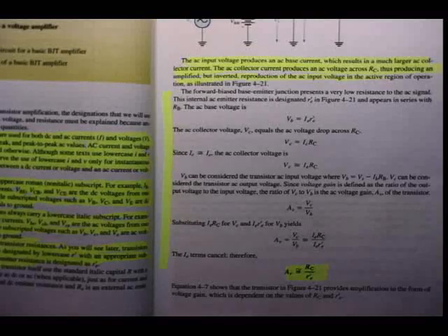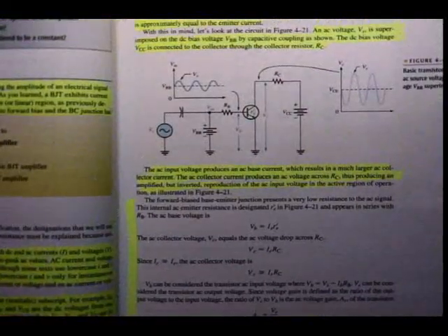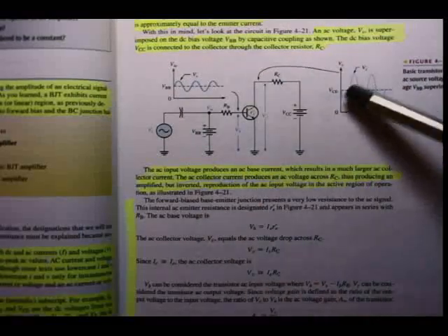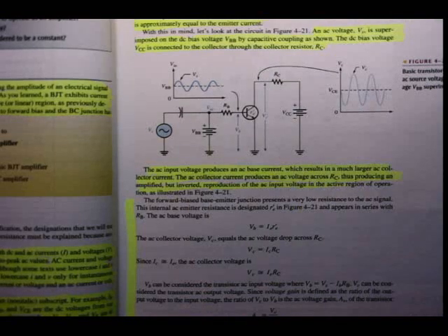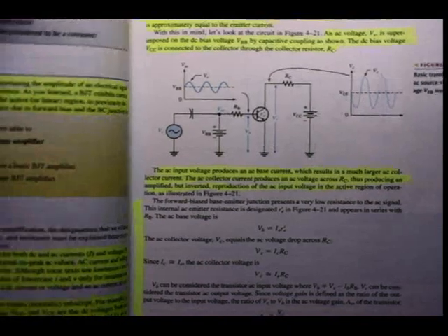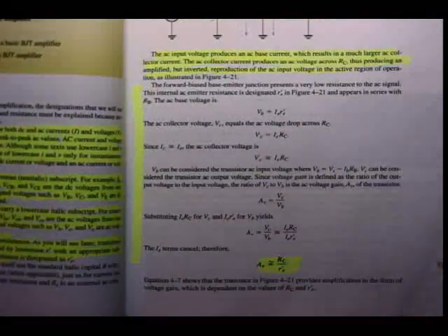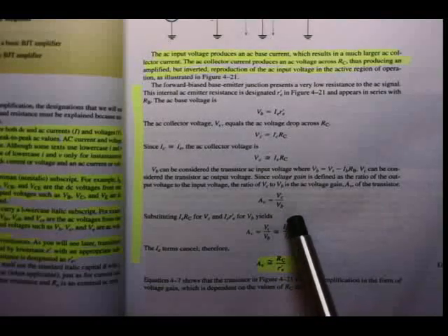that we have basically discussed already for VB, VC, because I can see from the circuit, if I refer back to the circuit again here in the textbook, the input is applied at the base and the output is taken at the collector. Now there's VCE. Alright, so to get this ratio, the voltage gain is a ratio. It will be the output divided by the input, which is VC over VB. That's why if you go and look at the formulas here, I want to determine VB and I want to determine VC. So in the end, the voltage gain is VC divided by VB.